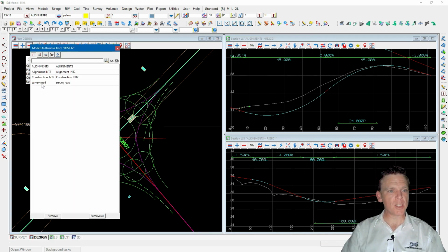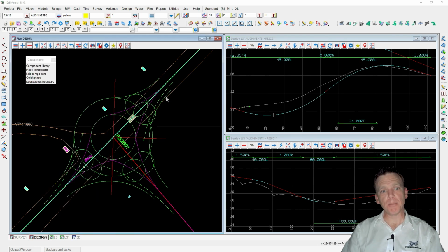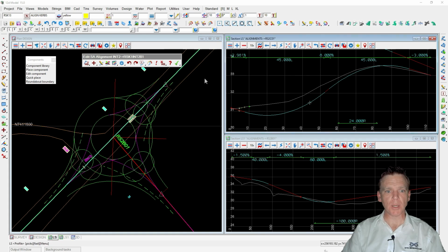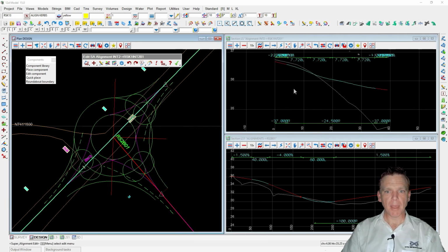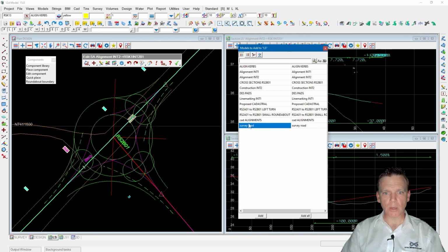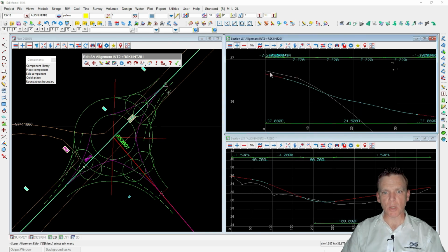Now I've just turned on a survey road string there, to show you how you can simply plonk one of these into a greenfield site, but then adjust the strings if you're happy to make it fit your brownfield situation. So I'm going to come in and adjust the curve return here, and we'll pull it apart and have a look at it both horizontally and vertically. So I'll come in here and have a look at it vertically. You can see it's being solved there. If I come in and show you the road, you'd obviously expect the survey to be up there where the tin is.